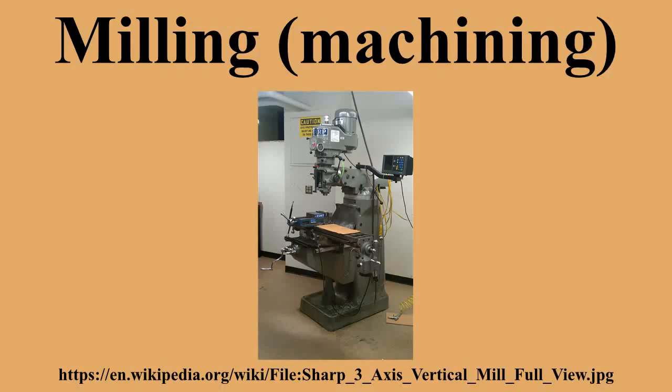As well, a mill drill often uses a standard drill press type Jacobs chuck, rather than an internally tapered arbor that accepts collets. These are frequently of lower quality than other types of machines, but still fill the hobby role well because they tend to be benchtop machines with small footprints and modest price tags.